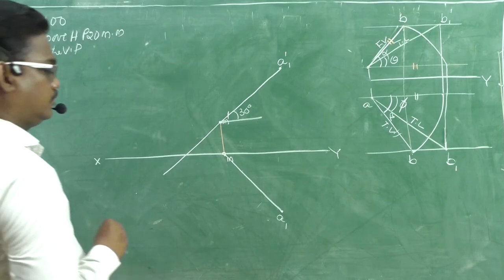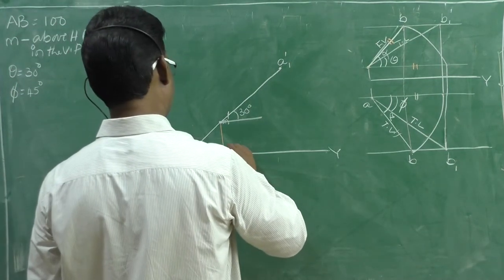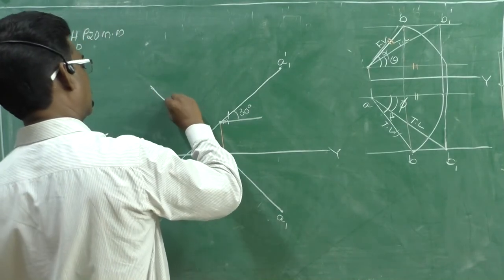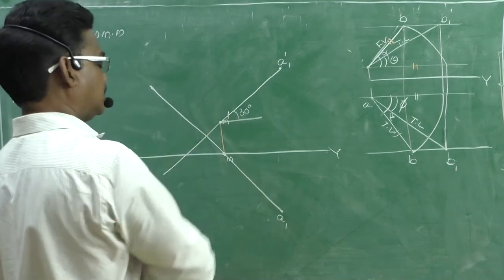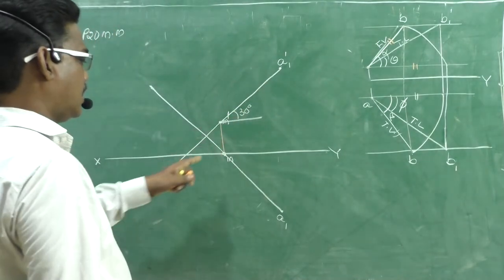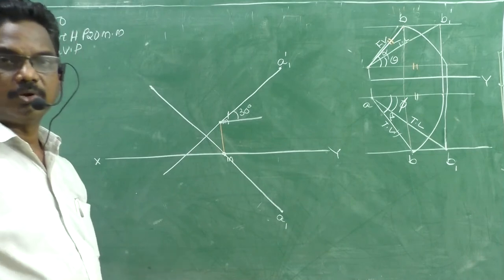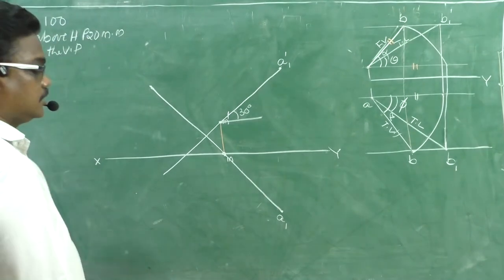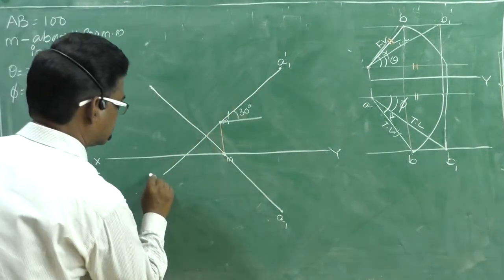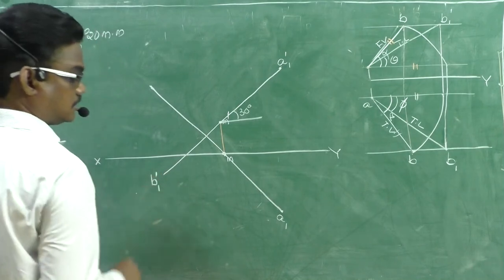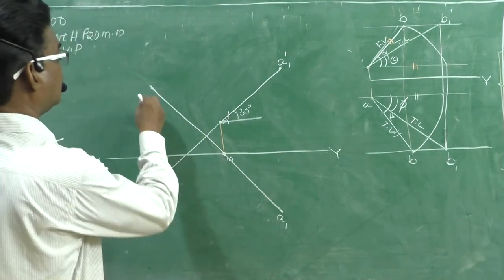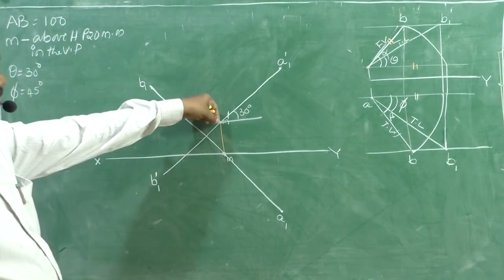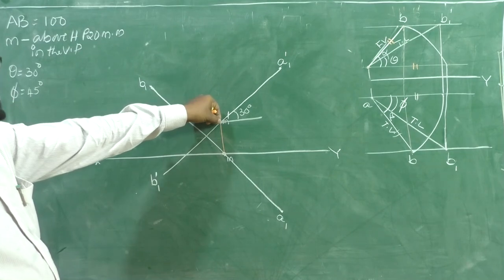Okay, remaining 50 mm. Extend this line for the remaining 50 mm. That means we draw the line with a total of 100 mm and fix the position of the midpoint. Now identify the moving points. Here this is A1 dash and this is B1 dash. This is A dash, A1 and this is B1. M is fixed, the midpoint is fixed.